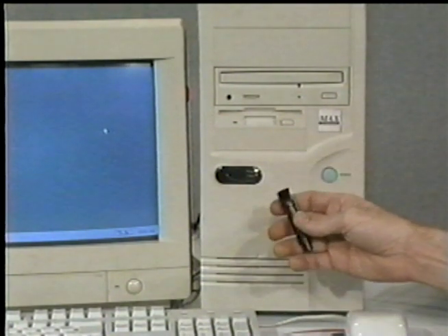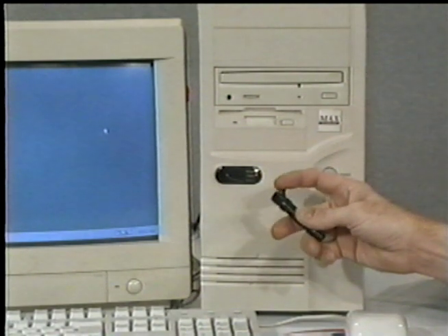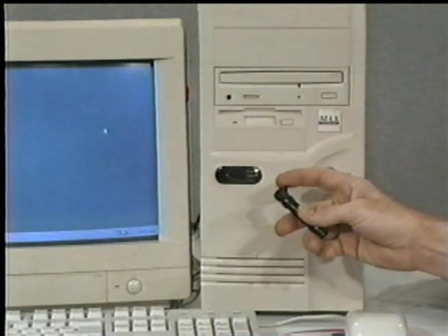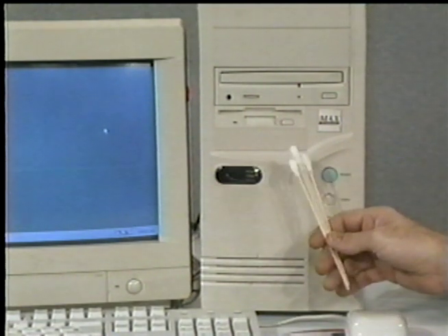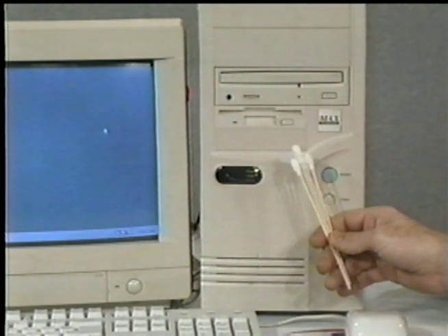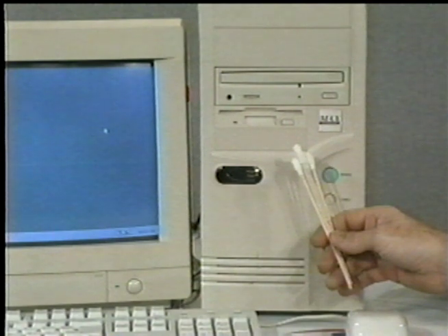A small brush, usually a paintbrush, can be used to carefully loosen accumulated dirt and dust before spraying with canned air. Lint-free foam cleaning swabs are used to wipe off electrical contacts and connectors, disk drive heads, and other sensitive areas. They should be made of foam or synthetic chamois material that doesn't leave lint or dust residue.